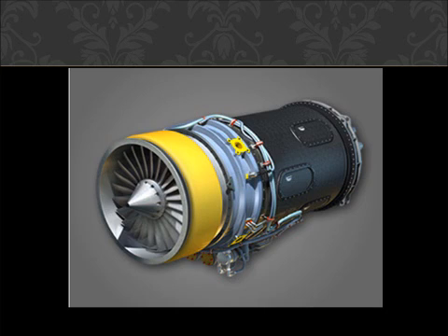Turbine engines must be accelerated to a high rotational speed in order to provide sufficient air compression for self-sustaining operation. Smaller jet engines are usually started by an electric motor, while larger engines are usually started by an air turbine motor. Before engines are to be turned, the APU is started, generally by a battery or hydraulic accumulator. Once the APU is running, it provides power, which is electric, pneumatic, or hydraulic power, depending on the design and the type of APU that is needed. So all these will start the aircraft's main engines.